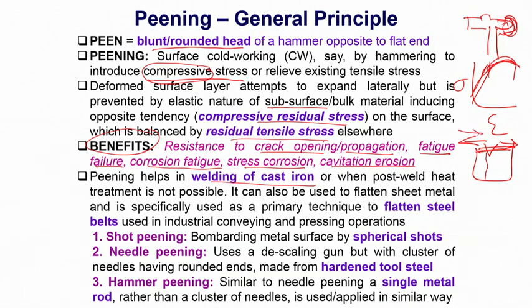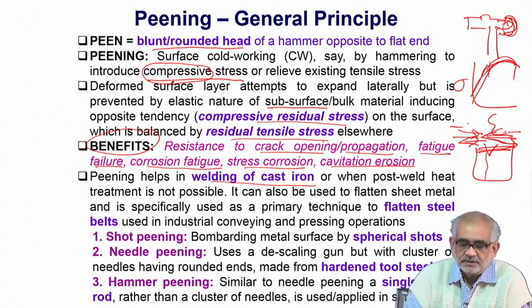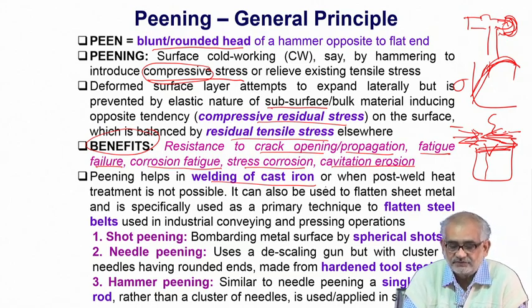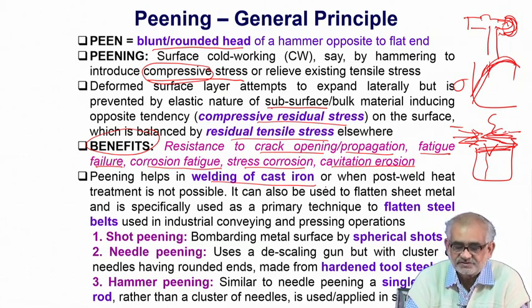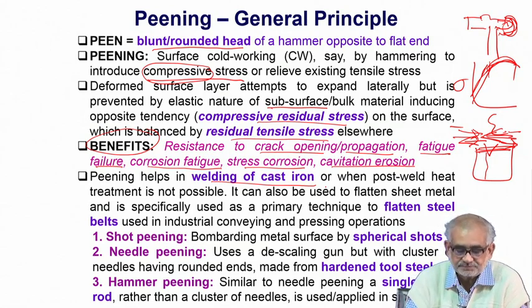So we would always prefer to have a situation where the state of stress is working towards each other, or compressive in nature. So for a welded zone, particularly at the root of the welded zone, if we can create such residual compressive stress by hitting with ultrafine spherical balls, then that is beneficial. It can be done on a flat surface, and it can be done even on curved surfaces or surfaces with complex geometry.